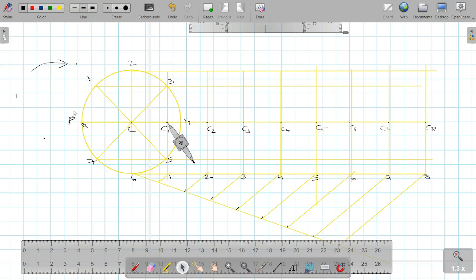In the initial case, till point number 2, it will keep moving upwards. So the marking will be on the left hand side. So for 1, the projector is this. This is the projector of 1. So we'll have to make a marking or an arc on projector 1 itself. So this is the cutting or arc.